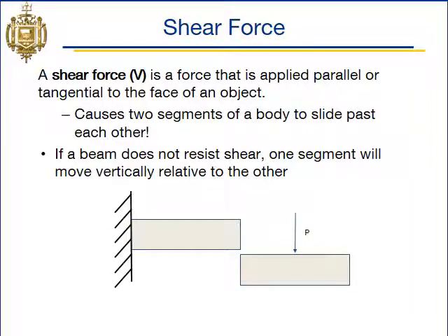All right, the second way that forces can flow through beams is via shear. In this picture down here, we have a load P in the Y direction. If we were to evaluate that load P on this area here, we would see that it's acting parallel to that area, and therefore we're getting a shear force and a shear stress.